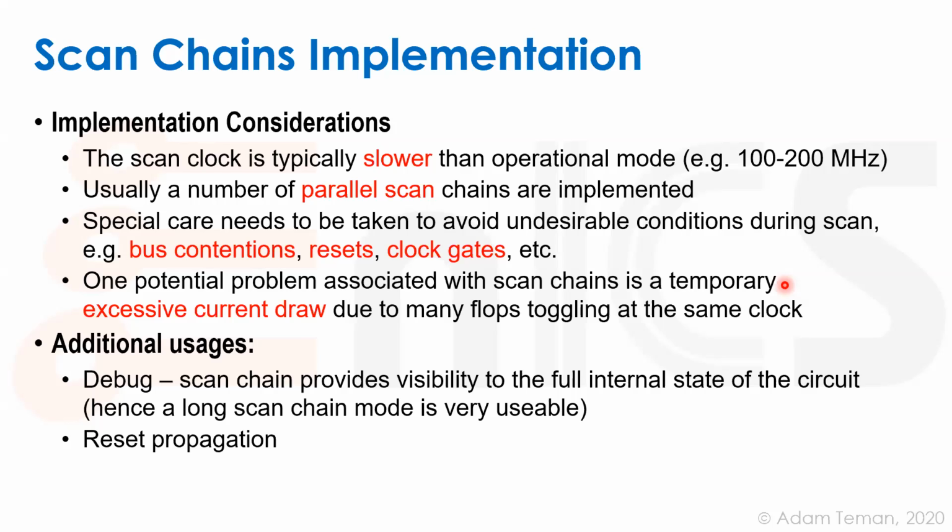Since you have this scan chain running through the design, you can obviously hack it and do all kinds of things, like debug with it. As Udi was saying, maybe use it for failure analysis. And also you can do things such as reset propagation and therefore get rid of reset pins, but I don't think that's commonly done, at least not in most parts of the design.